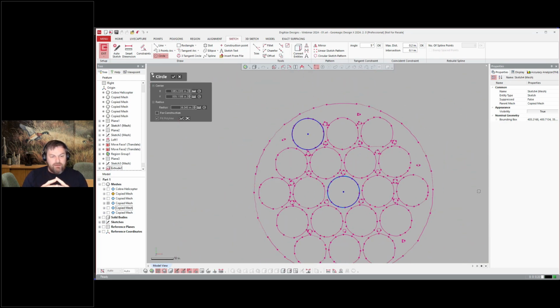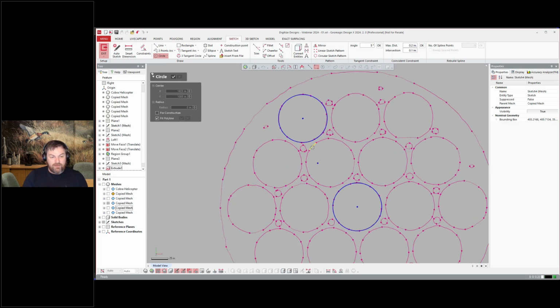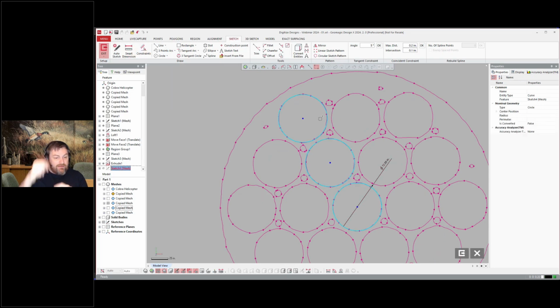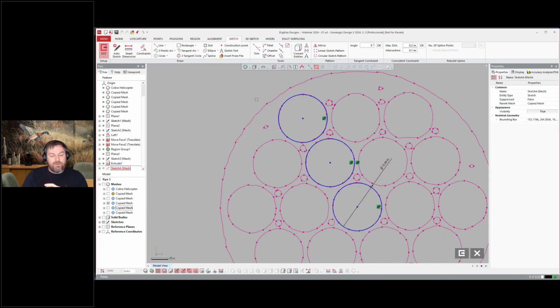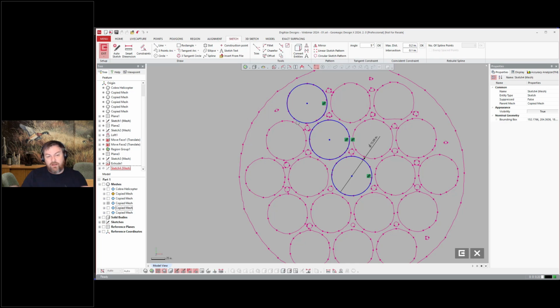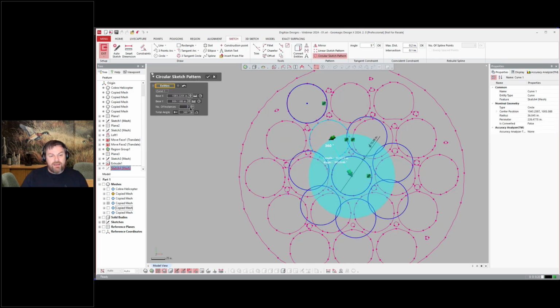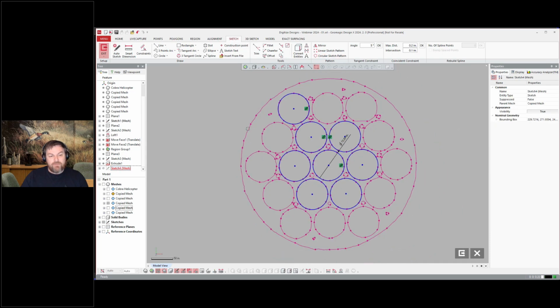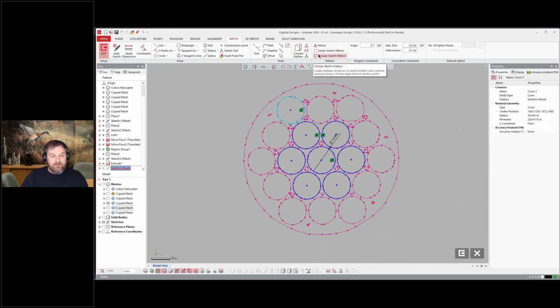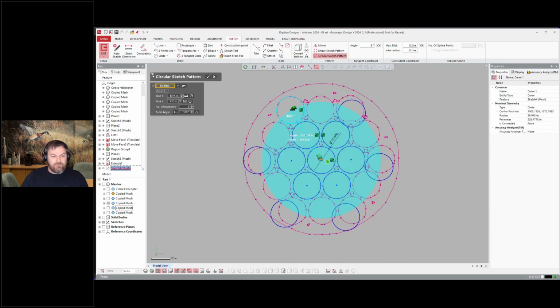Now I click on the end and I say, hey, let's go ahead and model some of these holes. Let's go ahead and model all of them, actually. And I recognize immediately that it's just a pattern, right? So you can say, I want to best fit a circle to these. I want to override it to this specific dimension. I want to make them all equal, so they're all equal radius. And then I want to say, I want to make this a pattern. So in this instance, I went ahead and patterned them on 3 individual patterns.